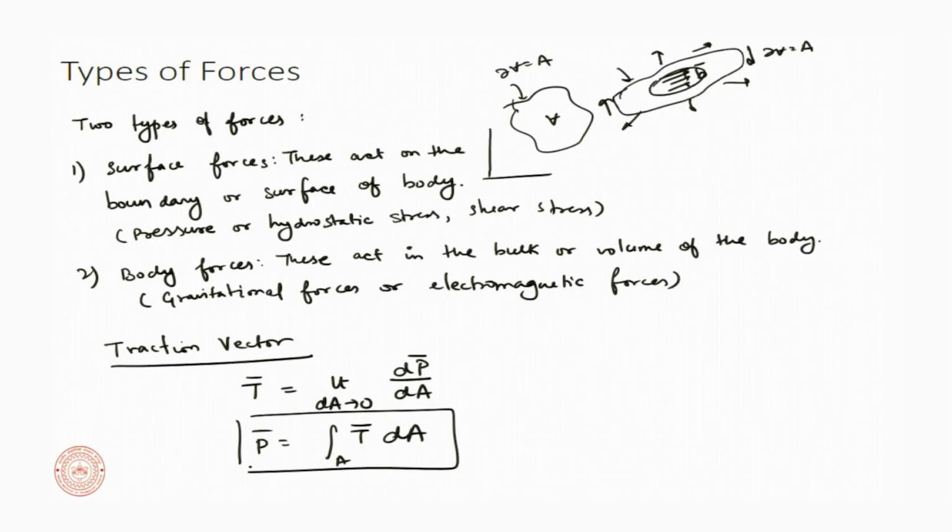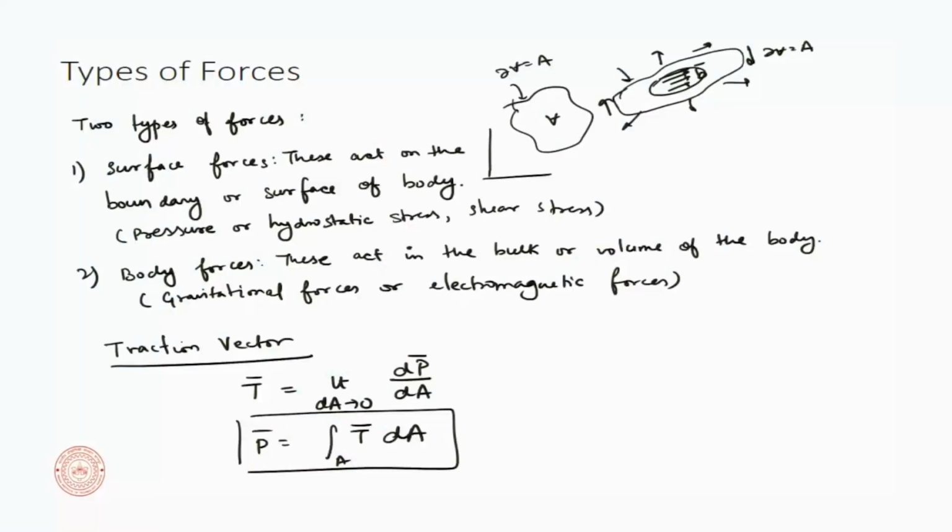So, what is a traction vector? Traction vector is, in a very crude or rudimentary definition, force per unit area. Okay, so this is what you would usually call stress in a UG level course or in your high school when you have studied solid mechanics or stress strain relations. Then the typical definition of stress was force per unit area. That was the case of a longitudinal body being elongated, if you remember, a body being elongated and stretched, then the load being applied on the cross section area of the body, that's what we called stress. That is not the definition of stress, that is actually the traction vector on the surface. Stress has 9 components, a vector has 3 components in a 3D coordinate system. Alright, so this is our traction vector and the load that we are getting is a surface force.